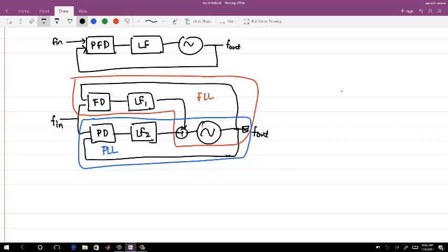Let me get to your question. You say, let's say your frequency detection has been done, frequency is locked, and my phase is not locked. If you are using the phase error detector which we have shown so far, you do not need a frequency detector loop to get the phase.